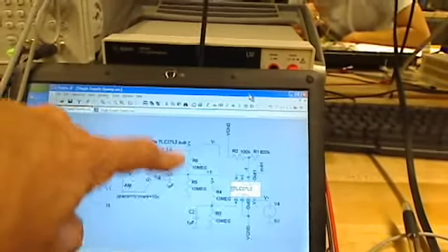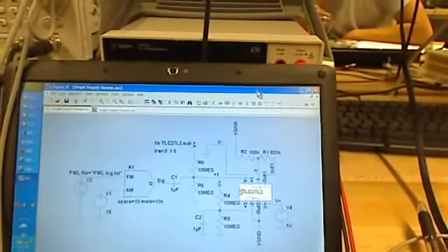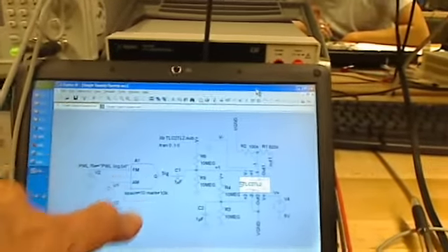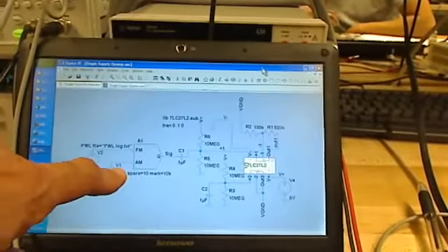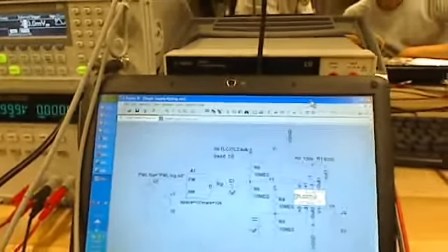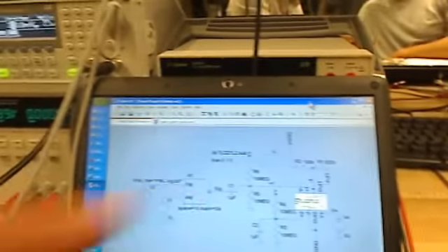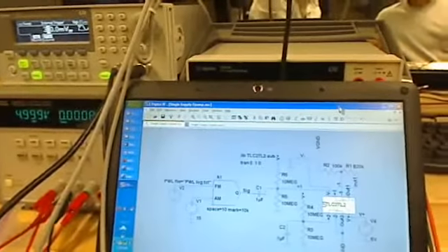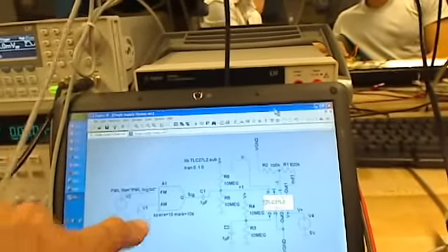I do have the 10 megohm dividers that I'm using to get 2.5 volts, and the 0.1 microfarad capacitor that I'm using to couple my AC signal, which is actually centered around 0. And you'll notice I've changed my space to 10 and my mark to 10K. That's because this is not a very fast op-amp, and you don't see much if you go to higher frequencies. I have 0.15 or 150 millivolts here because this sets the amplitude, not the peak-to-peak value of the output of